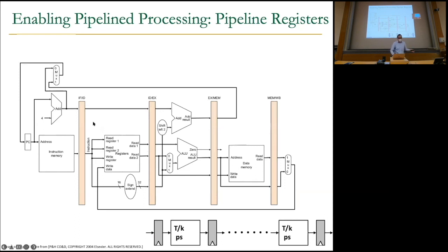They look nice. And we name them as, this could be called the fetch stage register, but instruction fetch / instruction decode register, instruction decode / execute register. Basically, they take the name of the stage previous to it and the stage after it. Execute / memory register and memory / write back register. So you need 4 registers.